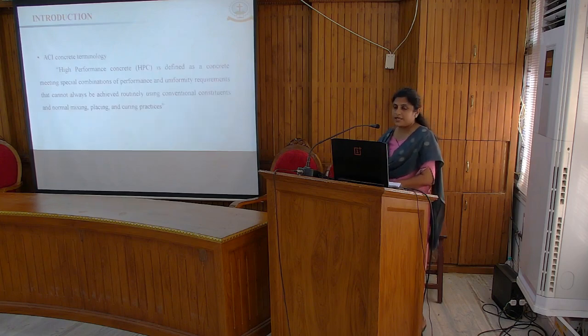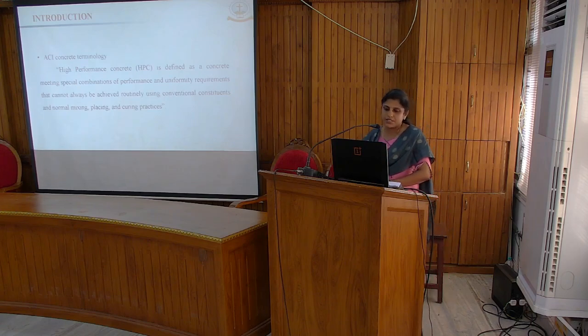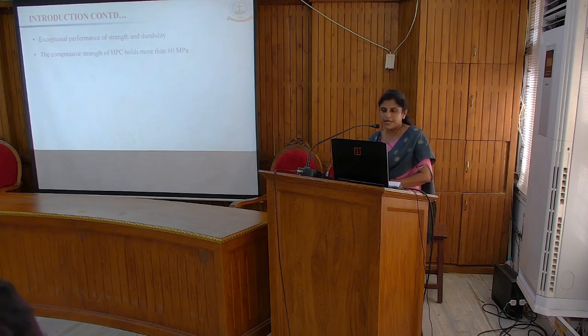As an introduction, according to the ECA concrete terminology, HPC is a concrete meeting special combinations of performance and uniformity requirements that cannot be achieved from normal conventional concrete. It has exceptional strength and durability. The compressive strength of high performance concrete is more than 60 MPa. Thus, it can be used in the construction of bridges, hydropower structures, pavements, mass concrete structures, etc.